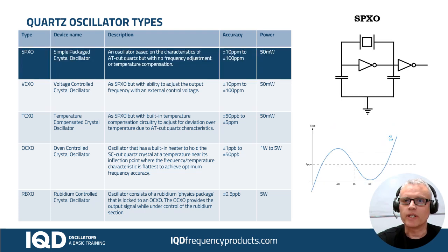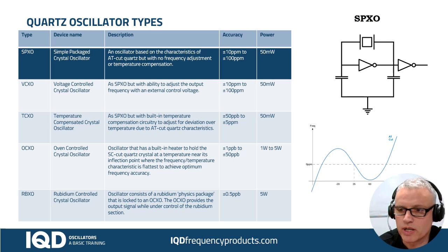And then we come to the next slide, where we're going to show a simple package crystal oscillator. Here what we're going to do is incorporate that rock into a basic circuit to make a resonator. Looking at the circuit, you can see the amplifier, represented as a buffer in the middle, a second amplifier which is isolating what's happening on the feedback circuit from the outside world, and then we see a couple of capacitors.